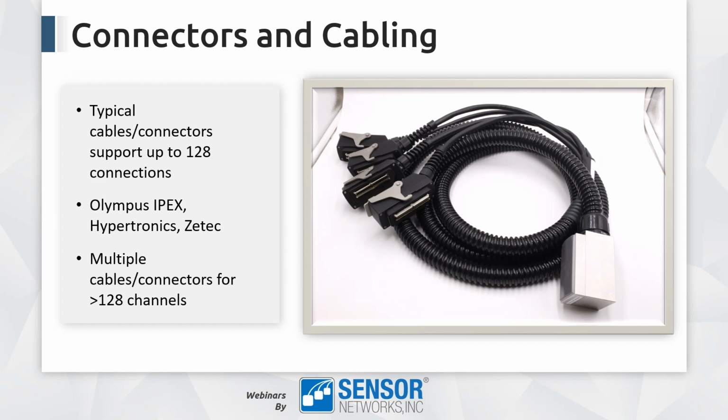Many industrial applications were using 128 or fewer channels, so for matrix arrays that use fewer than 128, the standard cabling usually works. But sometimes we get into scenarios where we have more elements. This shows you an array that we did that has 840 elements. It's a 1.5D array, so there's 420 electrical connections.